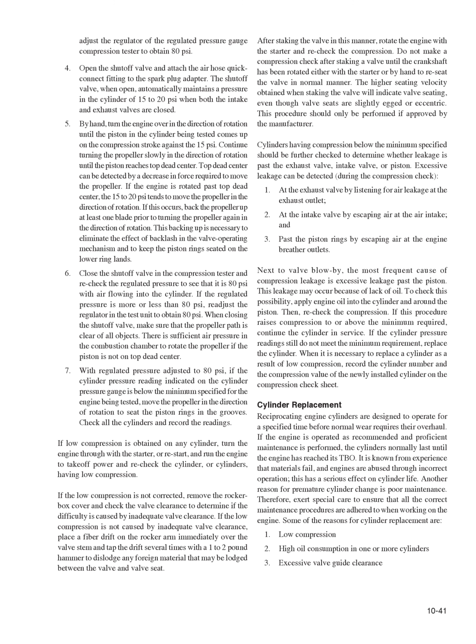If low compression is obtained on any cylinder, turn the engine through with the starter, or restart and run the engine to takeoff power, and recheck the cylinder, or cylinders, having low compression. If the low compression is not corrected, remove the rocker box cover and check the valve clearance to determine if the difficulty is caused by inadequate valve clearance.